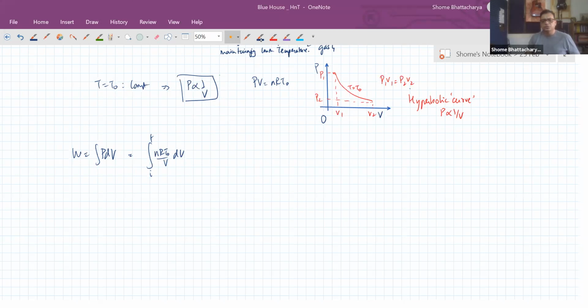These are laboratory processes only, and they have to be conducted very slowly, like I've explained. If we are compressing the gas isothermally like we're doing here, then the walls of the container should be made of conducting material like metal instead of insulator, and the load should be added very, very slowly. We should not add the load very fast.